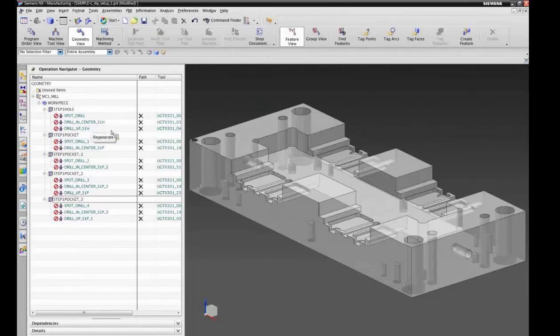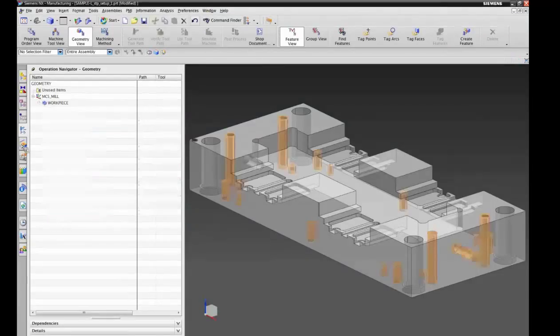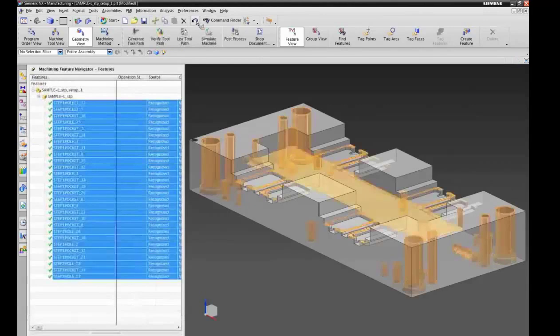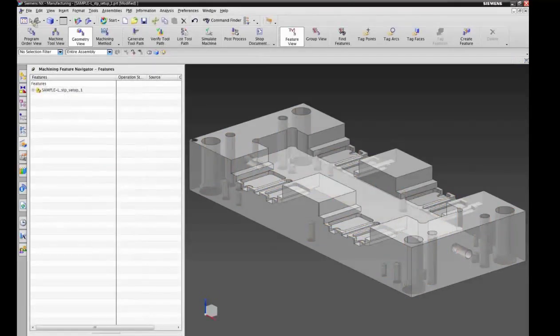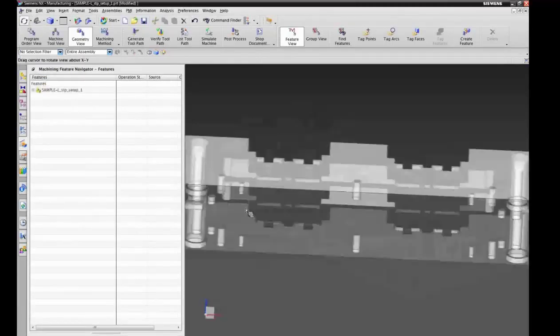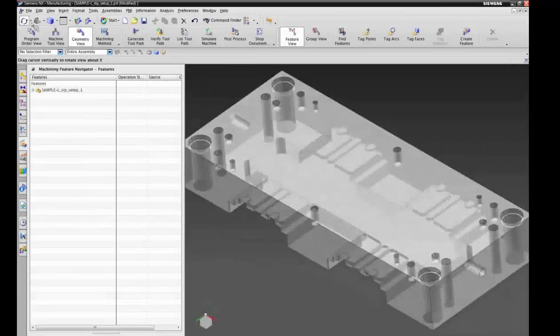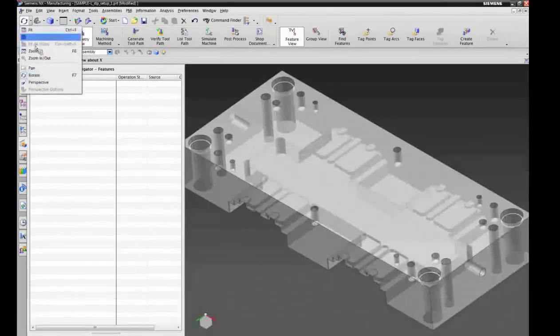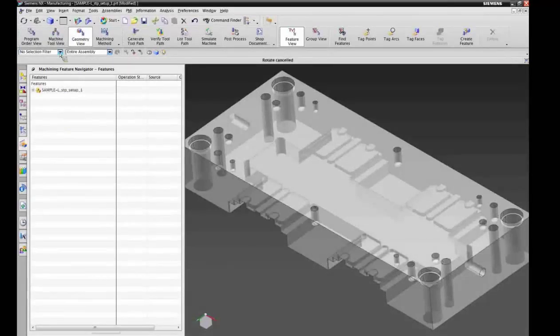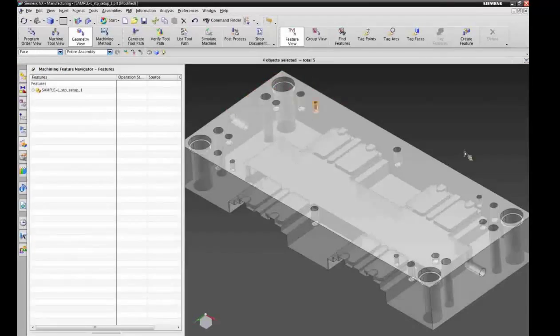Now, obviously, I could go into NX modeling and now maybe model some threads, but I'll remove the operations again, and I'll remove the features. There's an alternative there. And the alternative is to look at, as an example, color coding. Color coding is something that's a standard in many industries, and colors are nicely retained when exchanging step. So let me show you a few face selections.